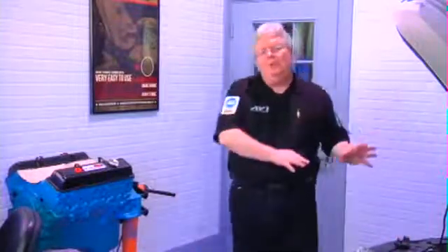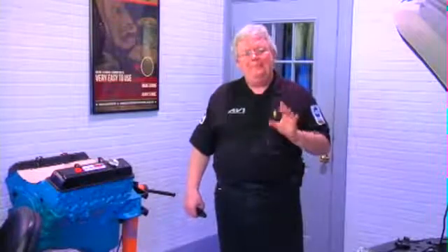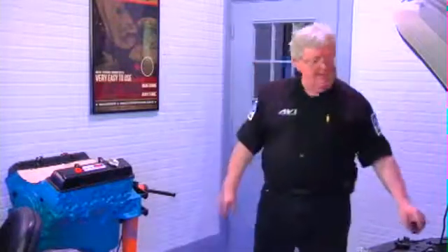While we've got this vehicle here in the shop, let's go ahead and get it hooked up to our GM MDI, the Tech 2 replacement. Vehicles of this nature, called the Global A architecture, that have 3 speeds of CAN data no longer work with the Tech 2. They work with its successor, the little MDI PC computer. Now we're going to take a look at that and look at some PIDs and see what we can do with electric power steering in the bay. So we get a little bonus here, learn more about how to pass your ASE A4, and also work on a new system you may see in your shop before you know it.